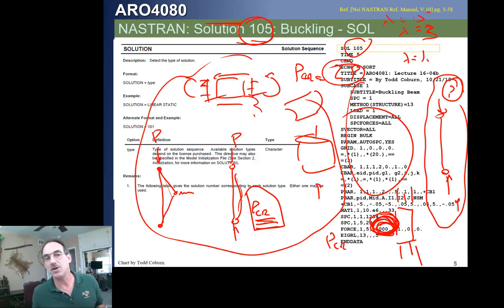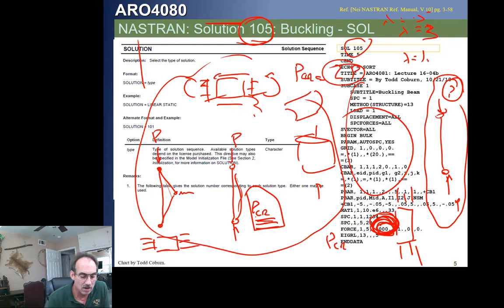Now often what we're going to do is we're going to get a bunch of eigenvalues. We're going to get an eigenvalue for every part in the model, every point, and then we're also going to get an eigenvalue for different modes. Remember when we were looking at the compressive buckling of panels. So let's say we have a panel buckling in compression like this. We saw the coefficient of buckling that we applied for our critical buckling load.